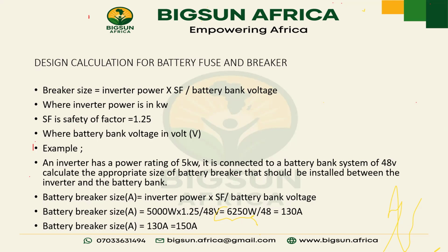Also, the charging algorithm of inverters is designed to deliver specific current based on what we call the BMS. The BMS in the inverter and the battery are synchronized together. That is why it's always very important that your battery, especially lithium batteries, and your inverter are communicating, so as to deliver the current that is needed to charge the battery at that particular stage.